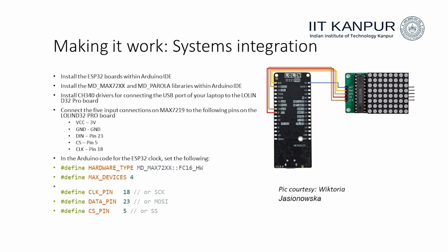If you look at the boards manager in Arduino, you can find the ESP32 board, and once you have found it, you install the board. You install the libraries for this display. And then you install some drivers for connecting the USB port of this board to the laptop. So for each one of them you have to do some installation.